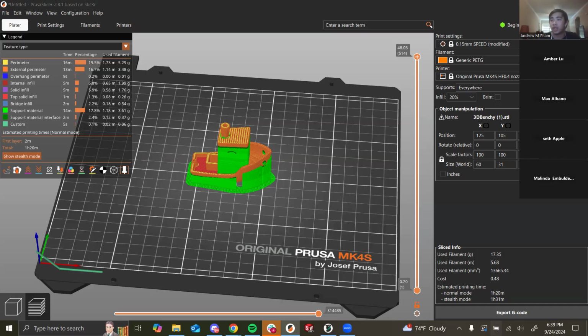Okay, that is a good question. What should you include in your screenshot? So the main thing I want to see in your screenshot is this information down in the bottom right. But if you just screenshot your whole screen, it'll give me a better idea. Here, like the info and layer height and material, along with perimeters all specified. So the only thing here that's missing is number of perimeters. And again, if your time was off, then I would know that you didn't do your perimeters correctly.